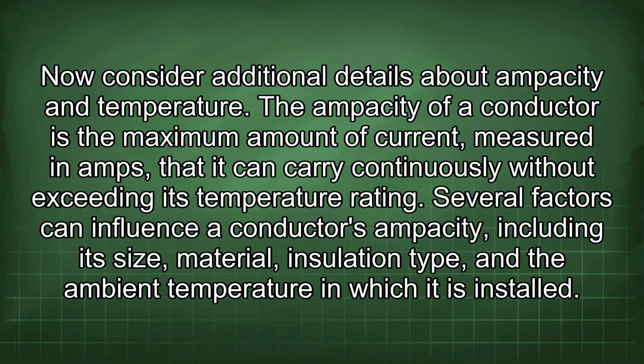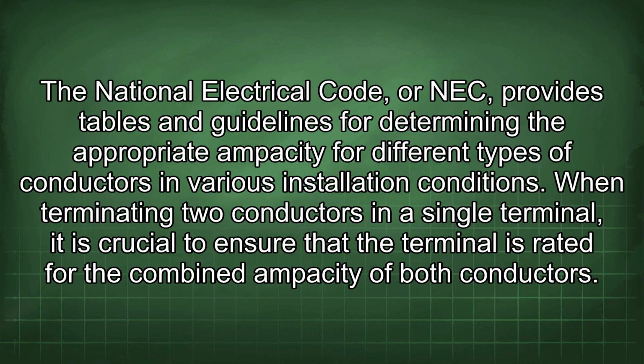The ampacity of a conductor is the maximum amount of current, measured in amps, that it can carry continuously without exceeding its temperature rating. Several factors can influence a conductor's ampacity, including its size, material, insulation type, and the ambient temperature in which it is installed. The National Electrical Code, or NEC, provides tables and guidelines for determining the appropriate ampacity for different types of conductors